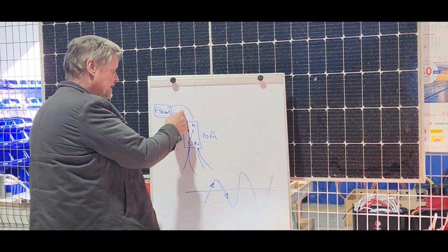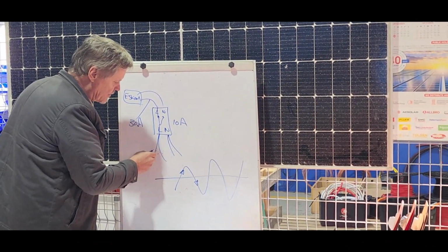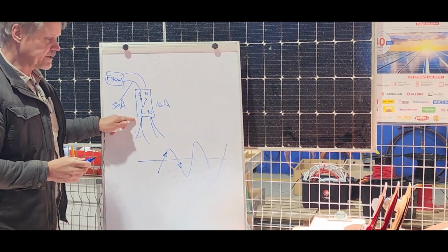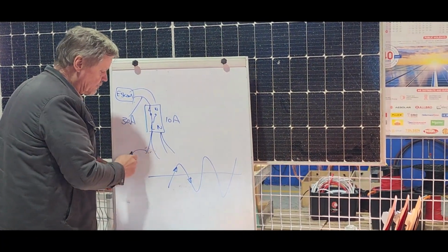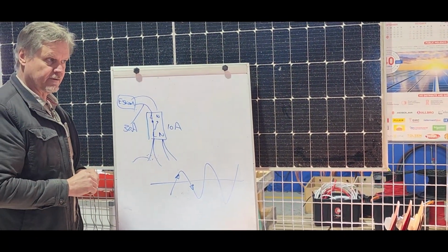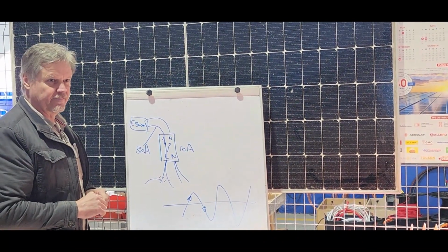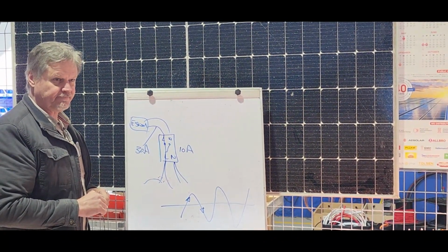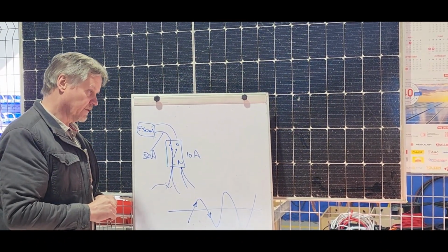So can I put my CT there? Yes. Can I put my CT just around one of the two cables? If there are two cables coming out of the live terminal, can I put my CT just around one of these cables? What do you think? Both of them. I agree with you. Why?